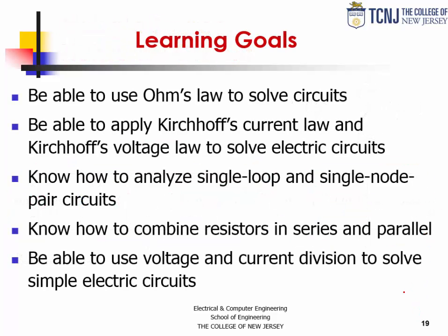So this concludes submodule 1.2 of the portion of the course, DC analysis. We saw and used Ohm's law. We showed how that applies to a resistor. We presented Kirchhoff's current law and Kirchhoff's voltage law, and we saw how we can use those laws to derive the equations for voltage dividers and current dividers.